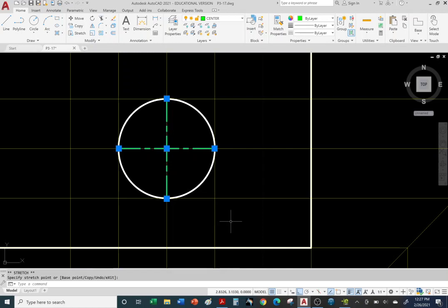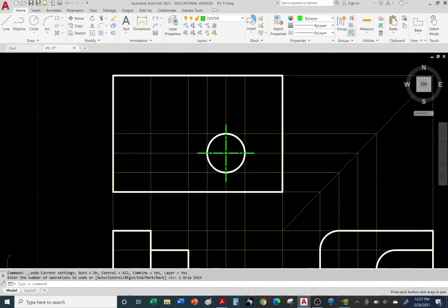So next week, in about a week, we'll get our next handout for chapter 3. And I will start taking points off if you forget to extend your green center lines. Let me hit escape and hit undo so I can go back to the extended. And again, just eyeball it. When you extend, if you're not sure whether to go short or long, it's better to go long than short on the extension. All right, so let's finish off the top view.